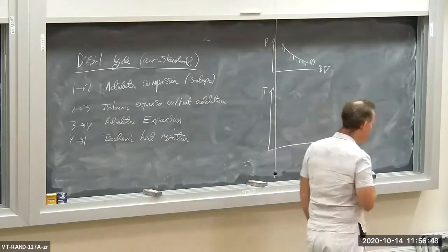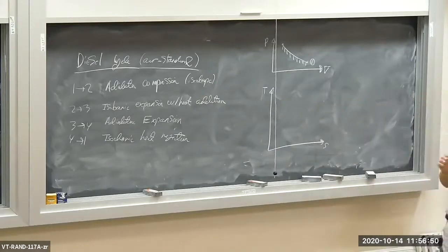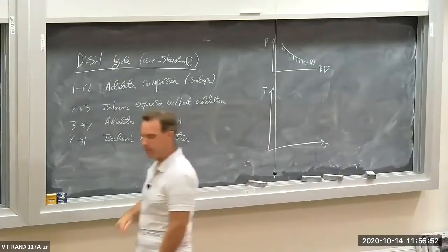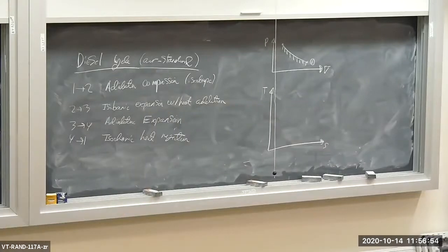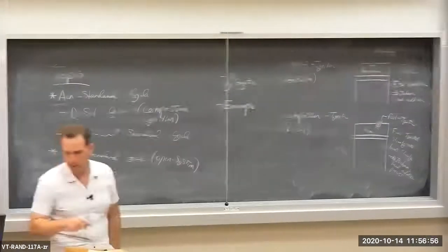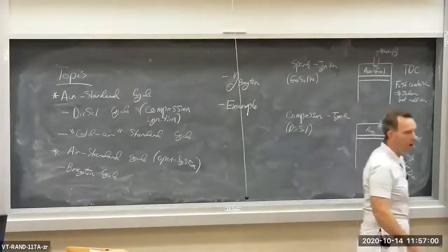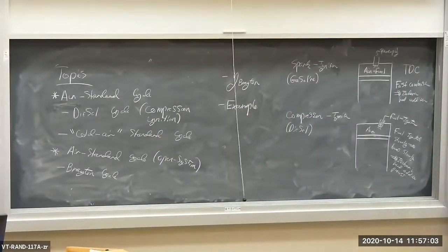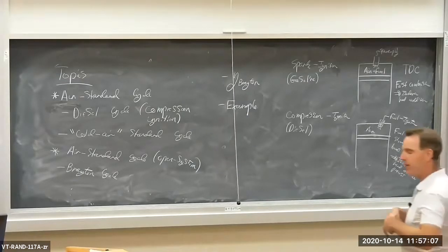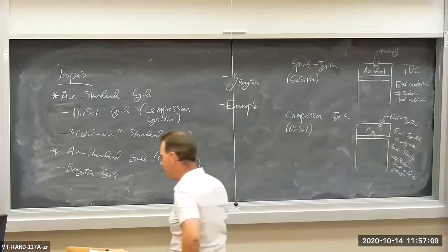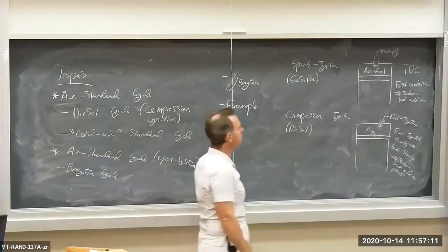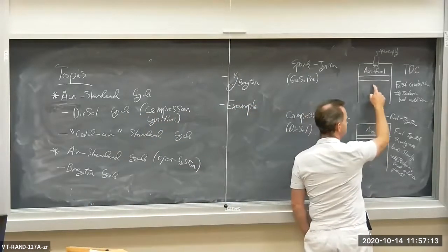We have air and we inject fuel when we want to start the heat release or burning process. For the Otto cycle, we start off with an already mixed air-fuel mixture, and then we initiate a spark and the heat is released essentially all at once, very rapidly. So we approximate this as an isochoric heat addition process.